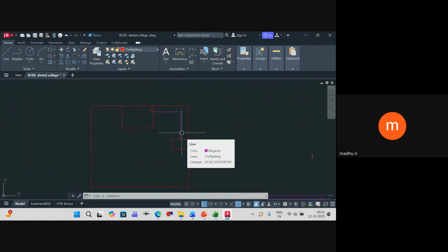Okay. Should we provide any pressurization here? No, not required, is it? Stairway pressurization, yes, we will provide it so that we don't want any outside air to enter into this. Exactly. Even with pressurization, there should not be any smoke penetration into this area. Yes, noted, noted. Okay.